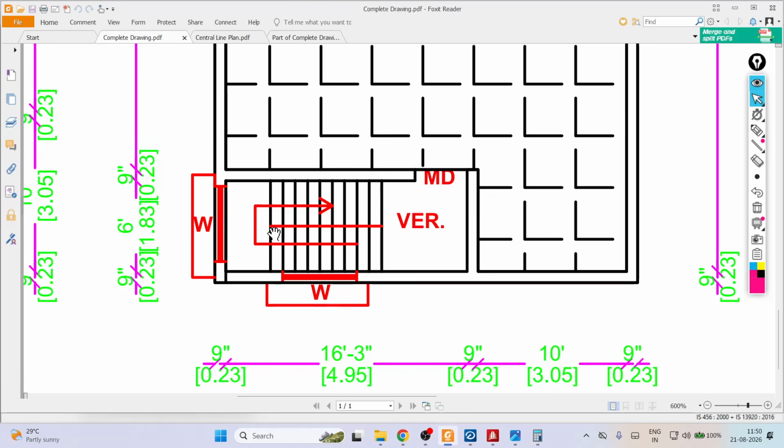Okay. So we know that floor to floor height is 3 meter. So landing would be 1.5 meter from ground floor or 1.5 meter below the above floor. So half landing we have, half stair we will prepare, then half a stair next time. Or we can prepare one time, and second time also we can prepare the half a stair. And in AutoCAD we can merge these two segments, so it will appear like one segment of staircase.